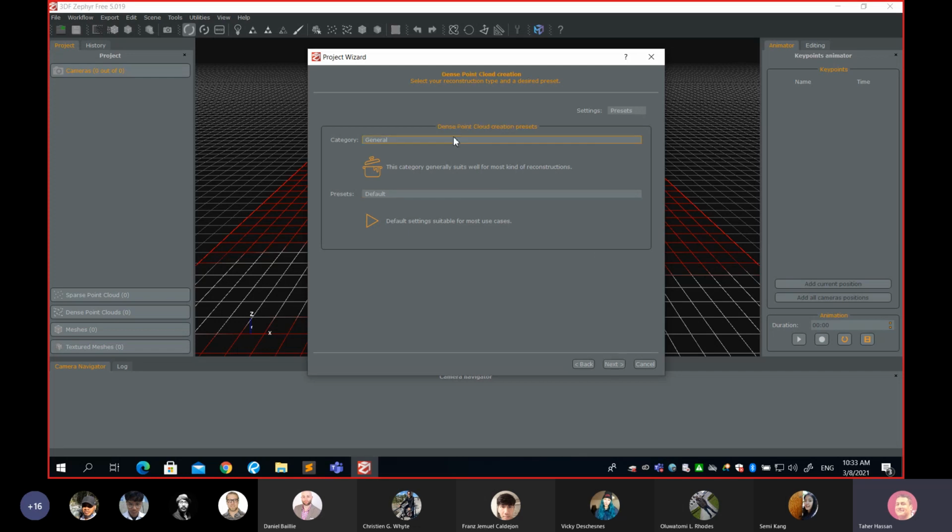The next one is asking about density of the point cloud creation. So the software will create a 3D surface for you. Now the question is, how many points do we need for my surface to be dense or coarse? The opposite of dense is coarse. Do I need a coarse surface or a dense surface? To be honest, everything has advantages and disadvantages. As I said before, if you need dense points, your software will have to spend hours and hours working for you. If you can live with a coarse surface, then it will do the job very quickly.